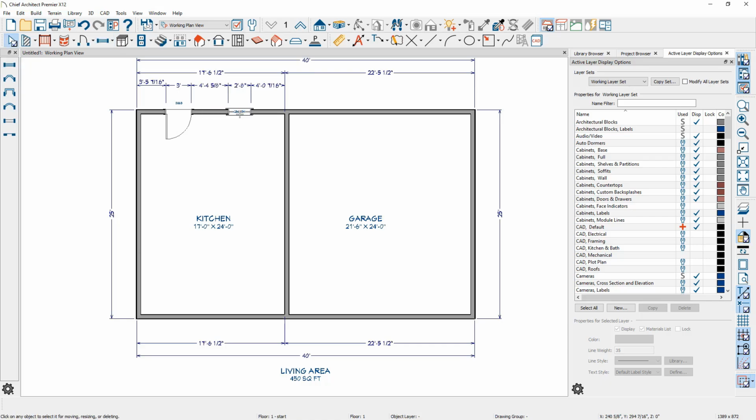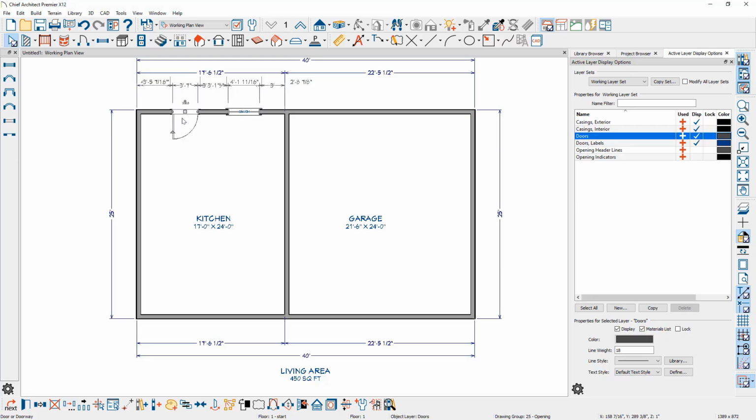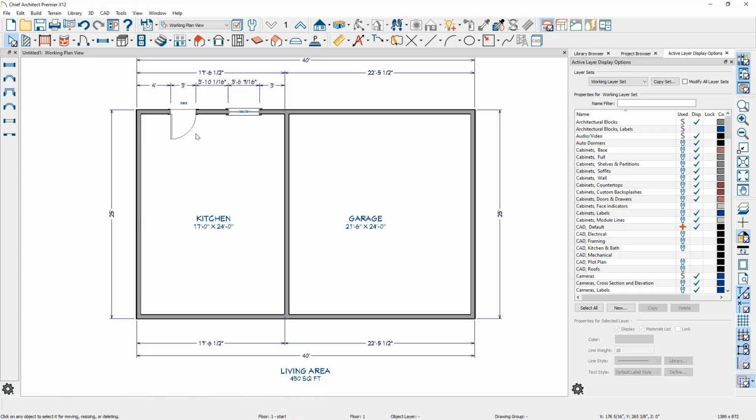Now, just like the walls, you can click on these objects, you can resize them, you can tap on the dimension, and then you can enter in a precise dimension if you don't want to slide it down the wall or click and drag it. So make sure the object is highlighted. Move your mouse up to the dimension. You'll see how my cursor changes to a finger. At that point, go ahead and click, and then you can type in the value that you want for that dimension. Now, the way these automatic dimensions have come in is they are actually going to the sides.